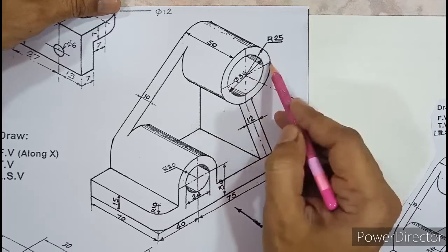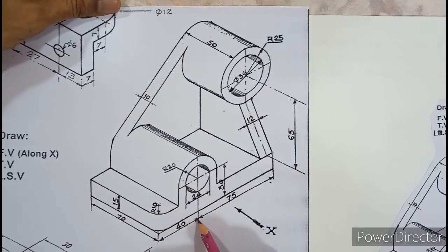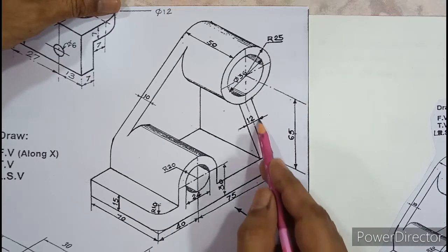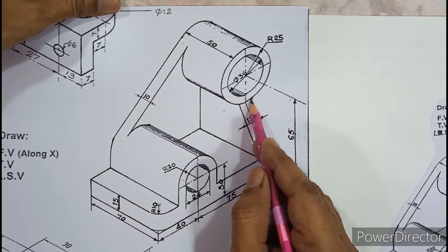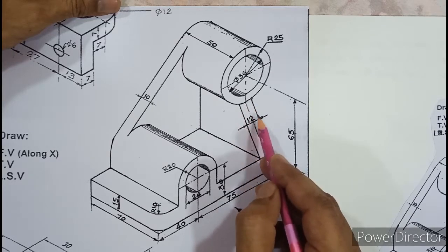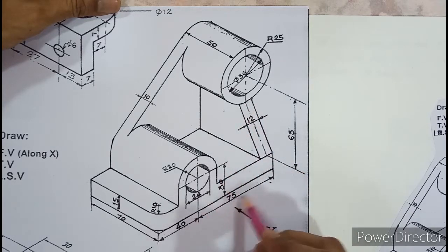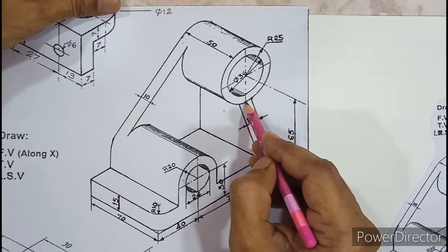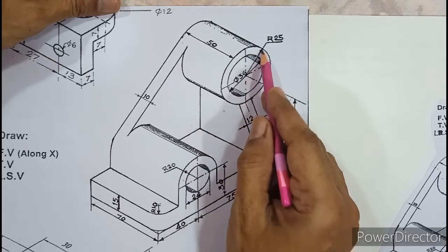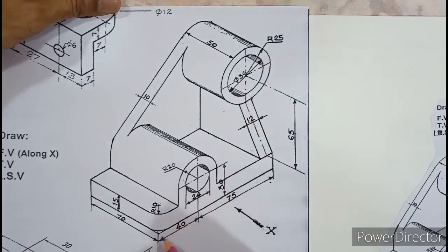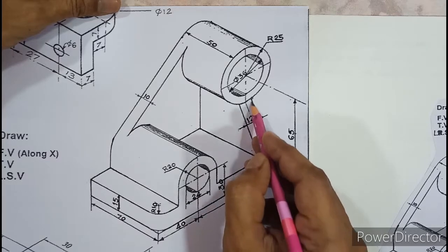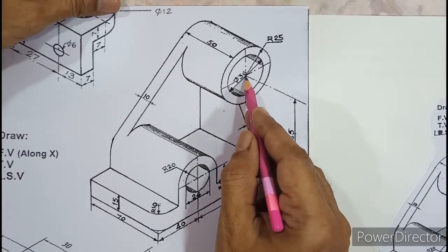So to get the exact length, what we should do is we have to add this 40 plus 75, move up. Then you have to come behind by 6 because half of 12 is 6. So 40 plus 75 minus 6. After minus 6, what happens is you reach the center and then you can add 25. So once again, let us see the length. From this point it is 40 plus 75, but 75 is till the end of the plate. You need to subtract 6 millimeters so that you arrive at the center of the circle